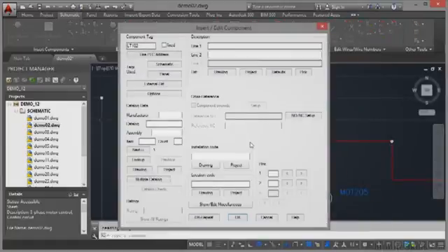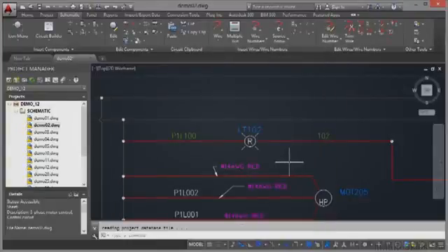It refreshes the drawing, and then as you can see, you're prompted now to insert or edit the component. We'll look at editing the components later on in this particular section. So I'm going to click on OK, and there's my pilot light straight into that particular wire, and you'll notice that P1L100 now is there, and we've got a new wire, 102 there, which is sequentially numbered from the pilot light onwards, because we've split that wire now into two wire segments running from one side of the component to the other. So that is how you insert components into your AutoCAD electrical drawings.